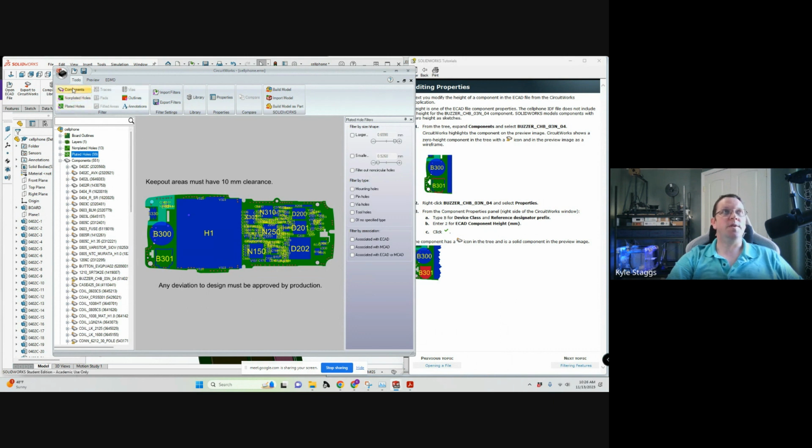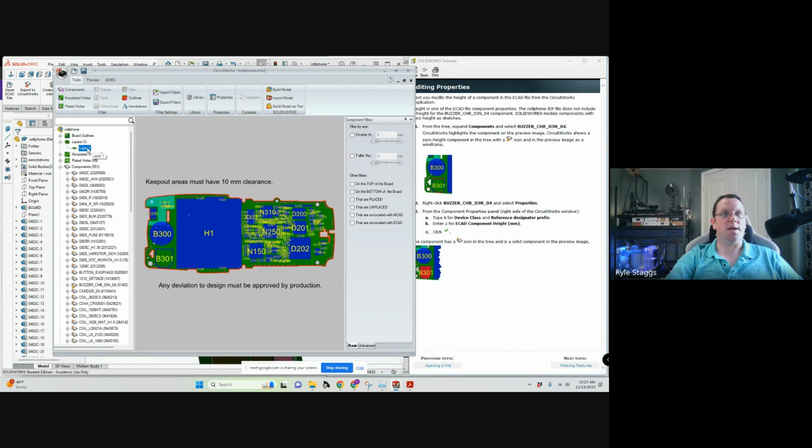So you can do different filtering. You can go back to just the outlines. You can look at some of the different layers. In this case, it really only has one layer, but there can be multiple layers. And then you can go back to highlighting the components and seeing which ones are which. Like this one is an antenna component X200.